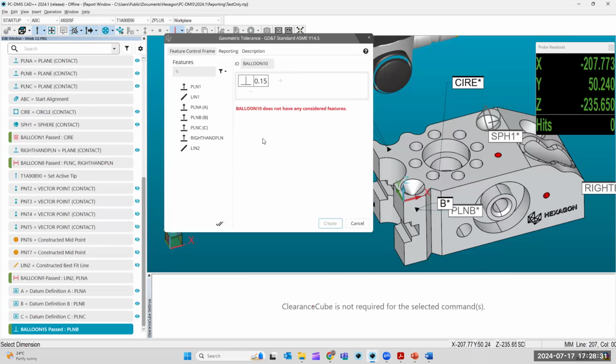I would have to label one of the datums, so that I have a primary and a secondary. I don't even need an alignment. It's a quick check to do because you have two 3D features that aren't dependent on an alignment. So you really wouldn't have to overthink that. If you have any other things you need to do, you probably want to do an alignment. But if you're just trying to compare two quickly, like if you're trying to check flatness, it's easy. If you're trying to check a plane's perpendicularity to another plane, it's easy. Yes, sir. Got it, sir.